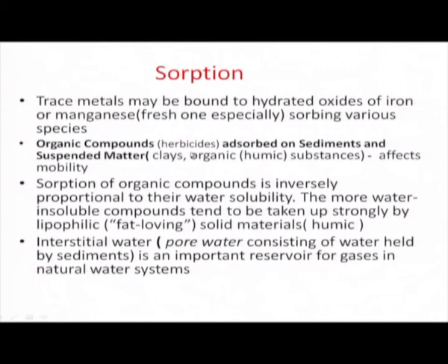And in addition to the trace metals, organic compounds like herbicides are adsorbed on sediments and suspended organic matter like clay and organic humic materials. This adsorption also affects the mobility of these organic compounds. Adsorption of organic compounds is usually inversely proportional to their water solubility, as I mentioned before, and more water-insoluble compounds tend to be taken up strongly by the lipophilic, that is the fat-loving or hydrophobic, solid material, usually in this instance humus material associated with the sediment.